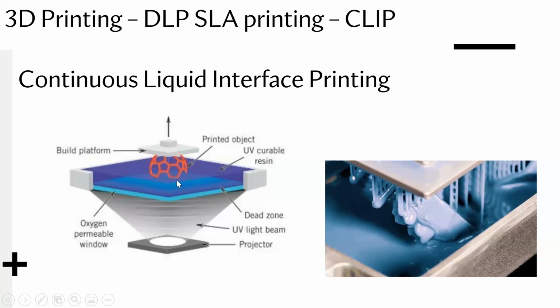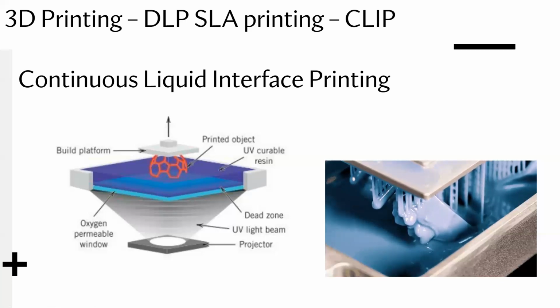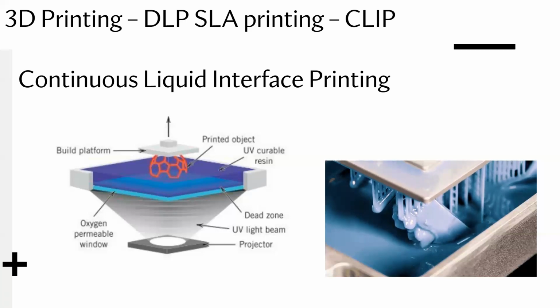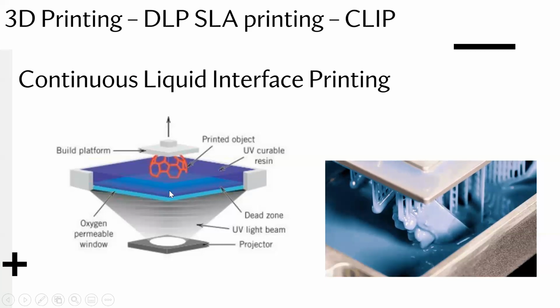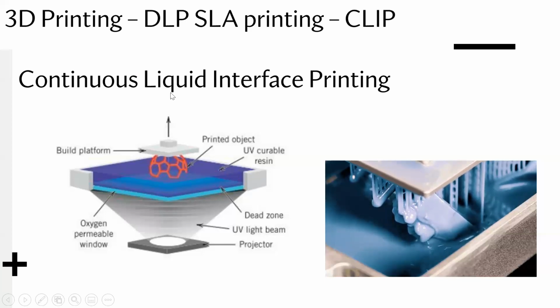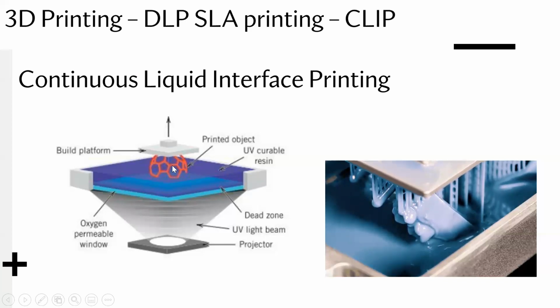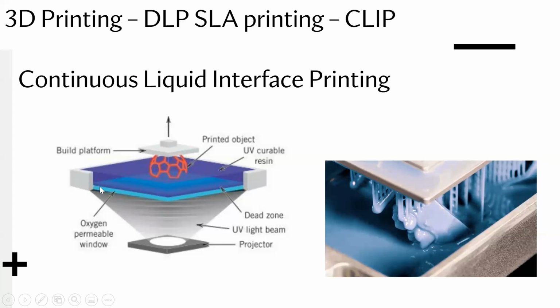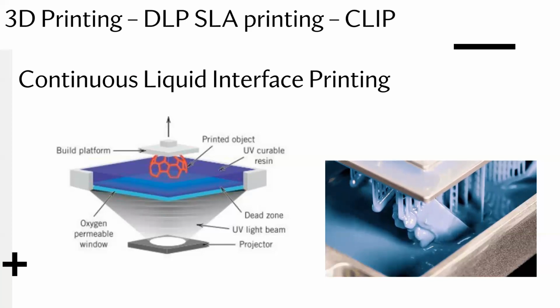And so, although you get curing a little bit further away, at the immediate neighborhood of this window, which is where we care about, you don't get any cross-linking, meaning that it doesn't stick to the window. And therefore, instead of doing this pumping process, you can continuously withdraw this object just because of this particular technology that you're using that allows oxygen to quench that layer and to avoid sticking.